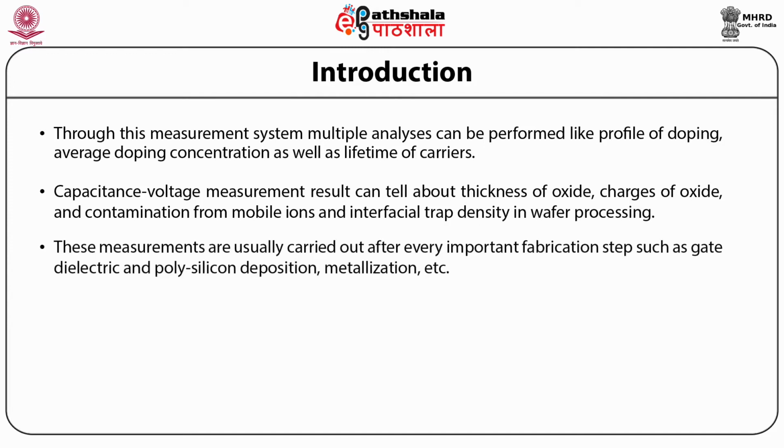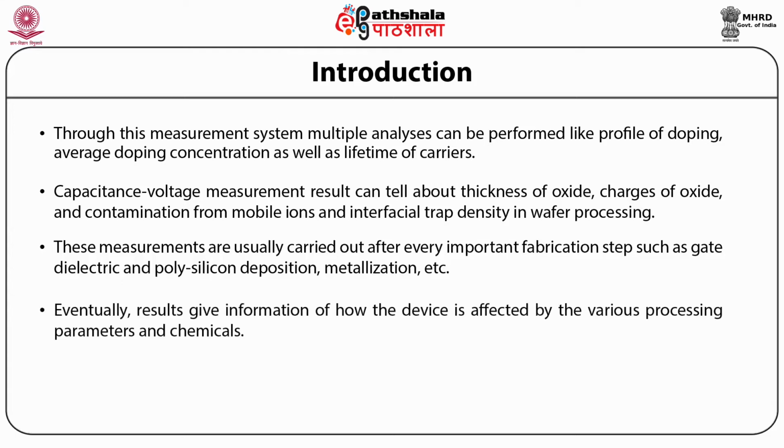These measurements are usually carried out after every important fabrication step, such as gate dielectric and polysilicon deposition, metallization, etc. Eventually, the results give information on how the device is affected by the various processing parameters and chemicals.